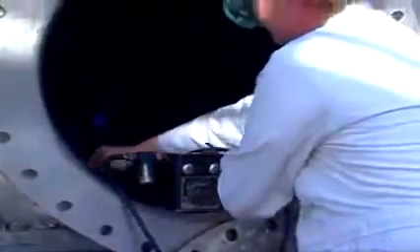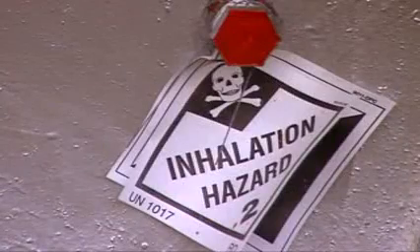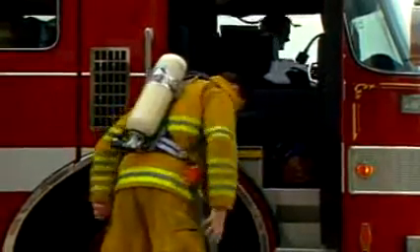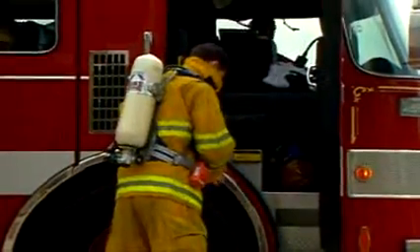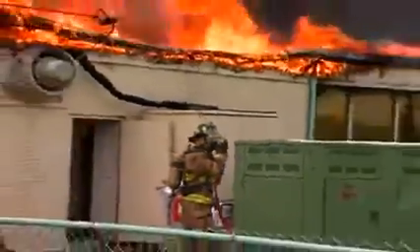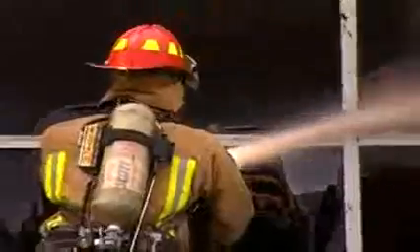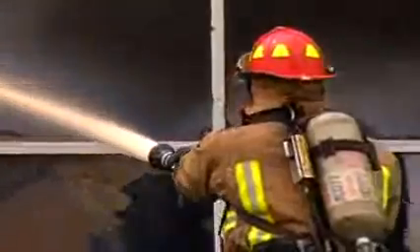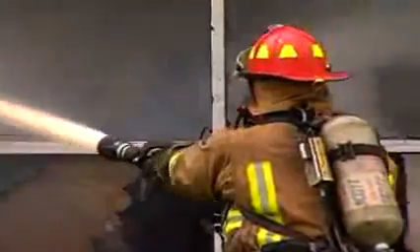These respirators can be used for entry into confined spaces and are normally used when there are extended work periods required in an IDLH atmosphere. A self-contained breathing apparatus, or SCBA, is similar to a scuba tank. The SCBA is commonly used in firefighting and can provide breathing air for an extended period of time. The SCBA consists of a wearable, clean air supply pack and doesn't restrict movement with a hose connection.